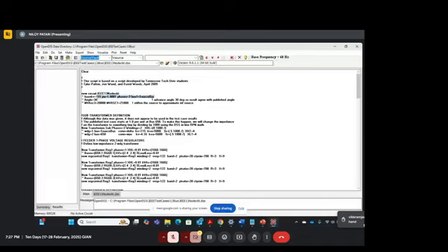Right now, the angle of the source bus is 30 degrees. The source bus is basically the substation node. Now it says advance angle 30 degrees, so the result is in degrees with the published angle. An angle of 30 degrees here means your reference angle at phase A is 30 degrees. Then phase B will be 120 apart, right? It will be minus 90 degrees. And your C phase will be minus 210 degrees, something like that.